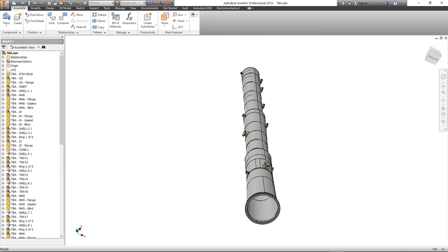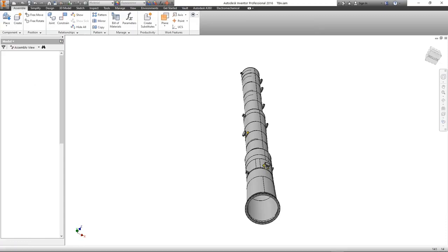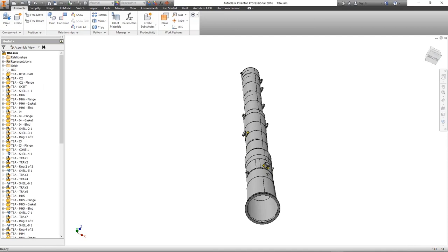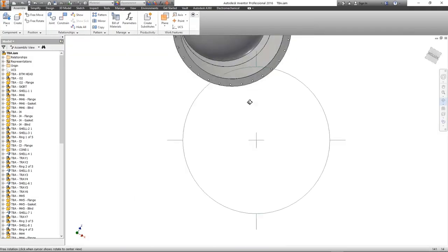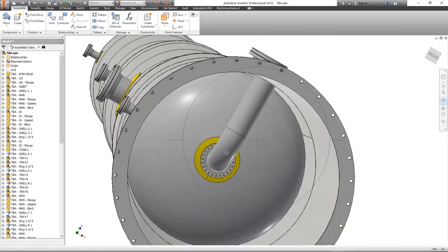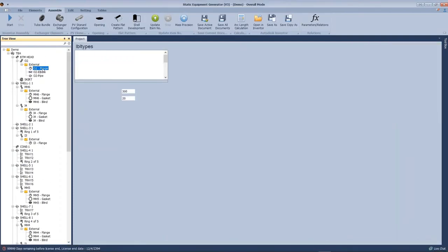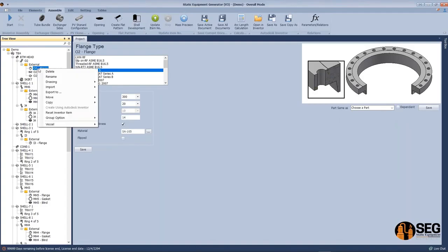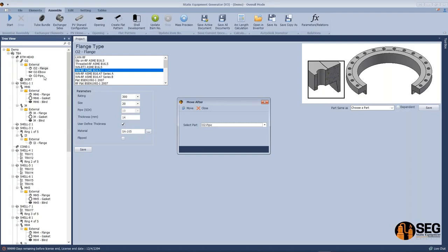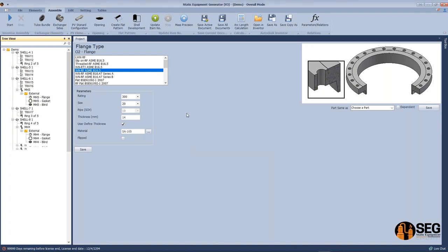And you have the ability in the settings to enable a preview, so you can see the model during creation, each element during creation, and I will enable this option here. You can see that we added this elbow and pipe, but the flange is still in place. The right arrangement is that the flange comes after the pipe. So we will move this flange after the pipe.